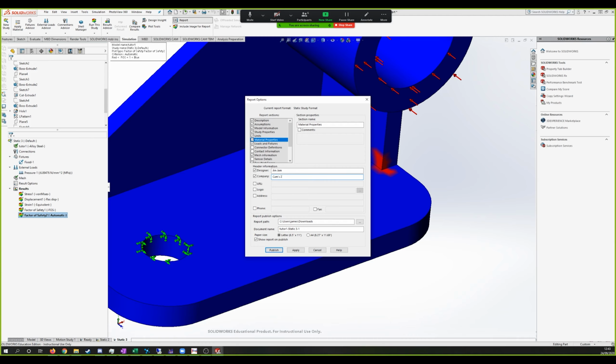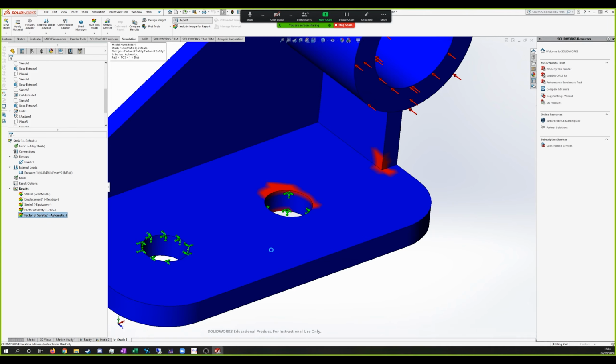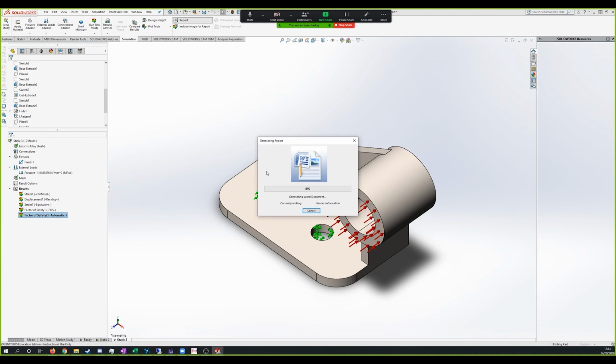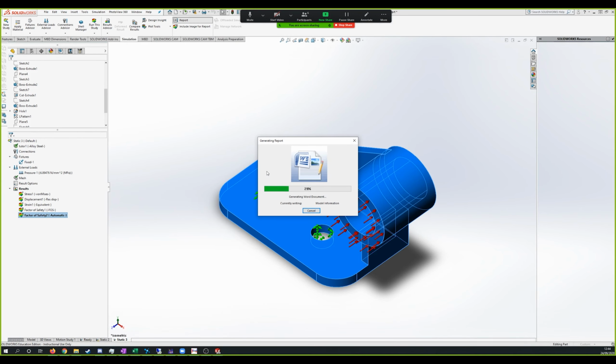So we have the part where we show the parts below minimum factor of safety, and it's those corner bits that you're talking about. Is that what you meant by it's got an affinity, or that just means it's below the factor of safety? It doesn't necessarily mean affinity. Yes. Okay, double click the factor of safety icon. The tutorial document on UTS Online has a method. It teaches you how to check for a singularity.